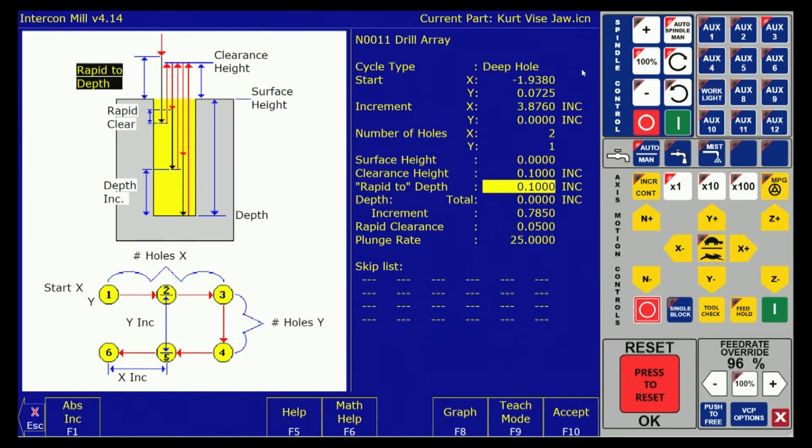So it's where the machine's going to rapid to in Z to get to our first hole. To the 100 height? Yes. We're going to leave it at 100. So what I said, I just said it wrong. We are going to rapid to 100 thou above our part, but it's this line that is deciding that. I can rapid and I can retract to different planes, I guess, what we can say here. Okay, depth.